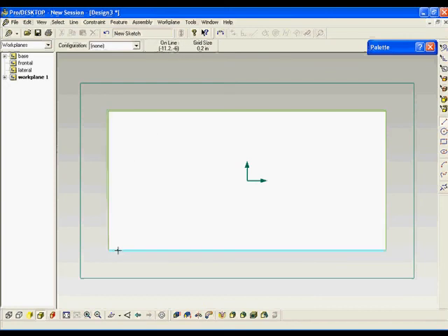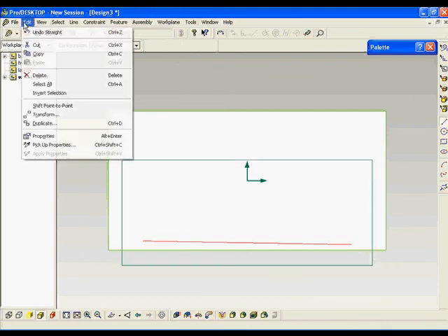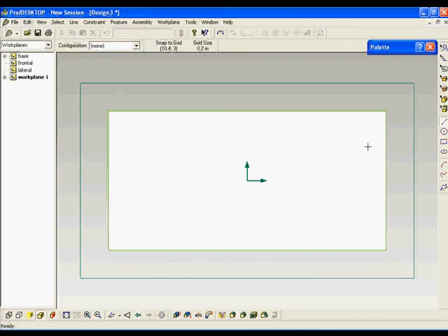I issue the straight line command, go to the bottom left of the rectangle, move 3 inches to the right, 1 inch up, and then click. Proceed holding the shift key down for an 18-inch line. If your line comes out crooked, just go in and do an edit undo. Click on the straight line again. And my new coordinates that I'm going to start my line at is going to now be -9 and -5. Click, drag 18 inches, unclick.